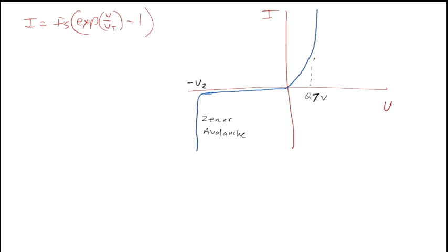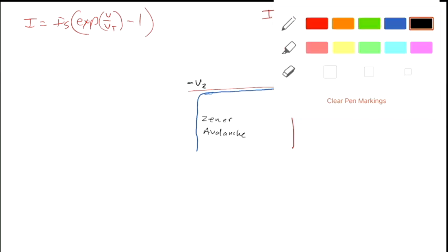And the Zener effect is by applying such a large voltage that the covalent bonds holding the silicon together are actually broken, and you create a whole bunch of free electrons and holes that way. But it doesn't really matter which is which, and you can't really detect the difference so easily. That reverse breakdown will occur at some voltage VZ.